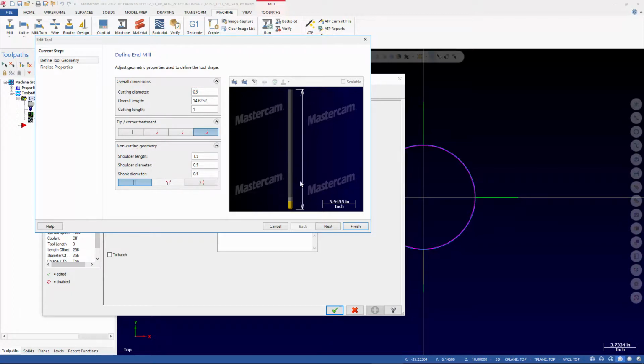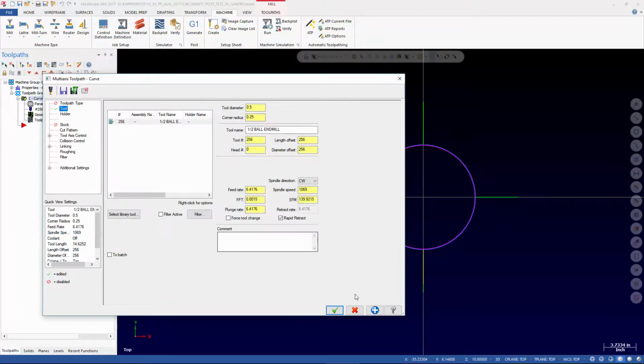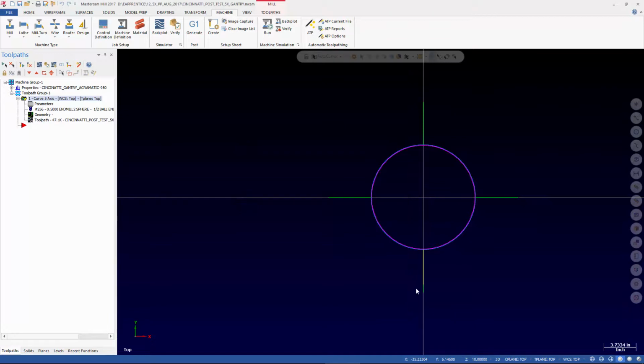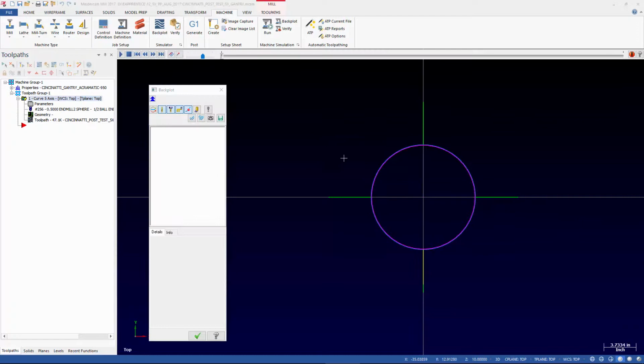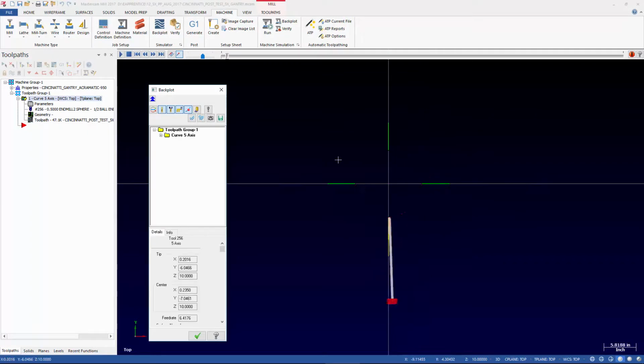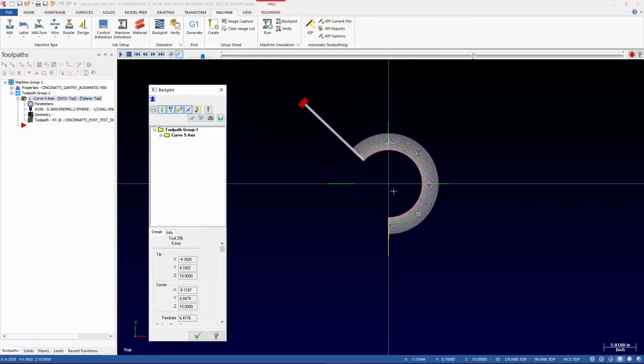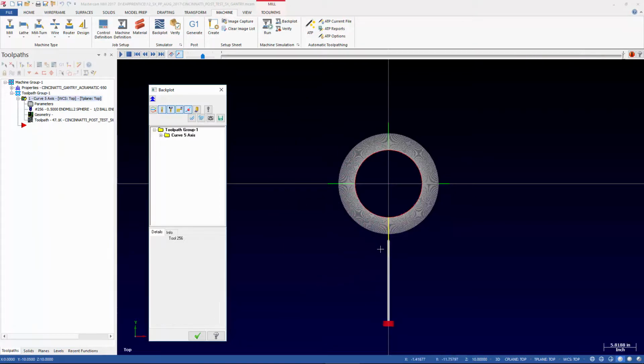And I can put in the pivot length as the overall length of my tool. Now, what's the disadvantage of doing it this way? This is the disadvantage. It changes your graphics, and so it doesn't let you use the real tool length that you're sticking out and the holder and the whole 9 yards, which kind of sucks, to be honest.